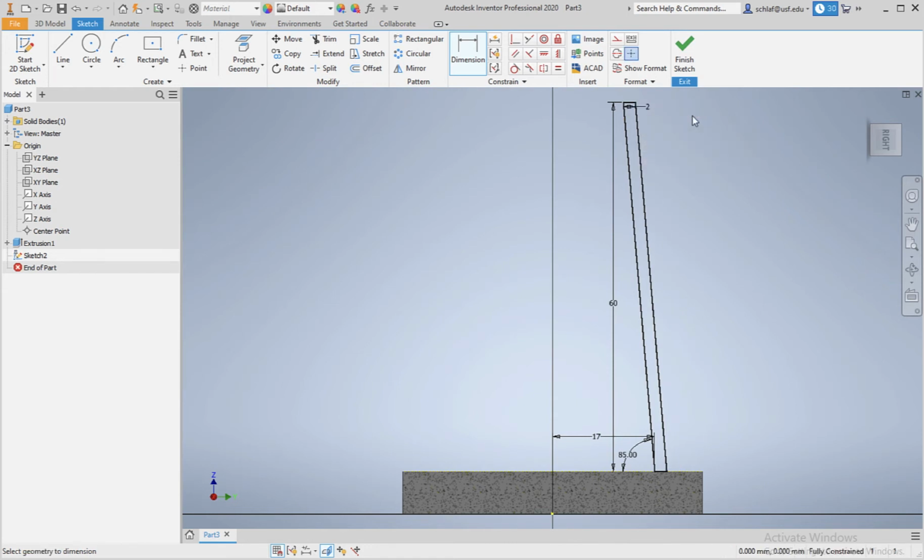Why do I choose 2? Because 2 is a really great sidewall thickness for 3D printing. It usually comes out in a high quality without any funny wiggles and stuff. When you go thinner, it can stress the 3D printer a little bit depending on the model you have, and so it doesn't look so pretty anymore. So 2 is a good number for a wall that you print upwards.